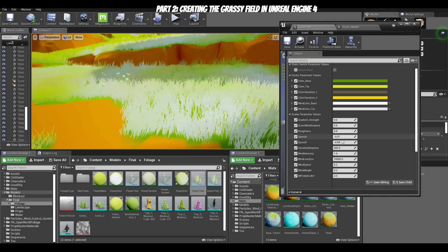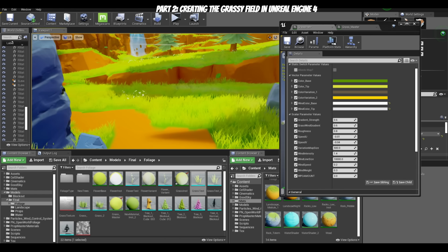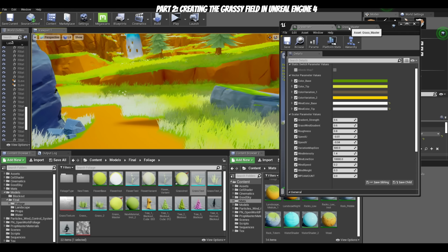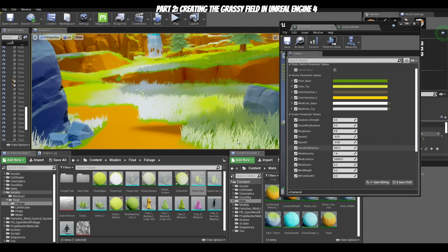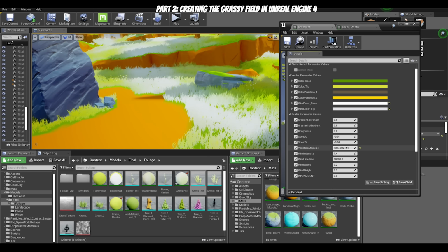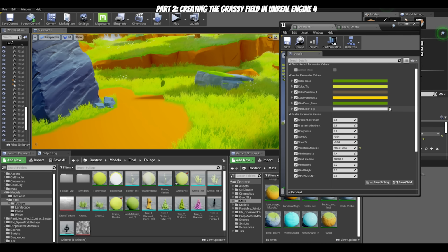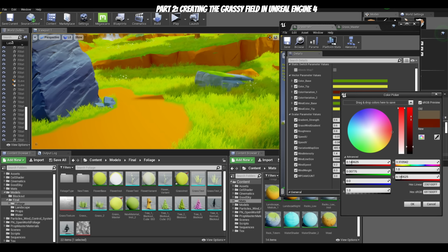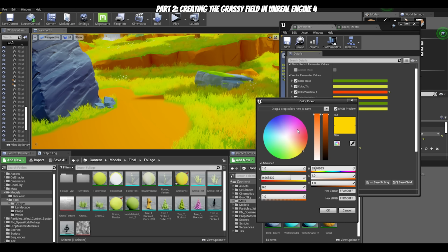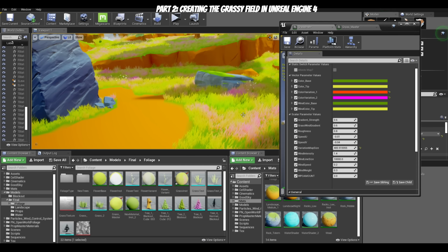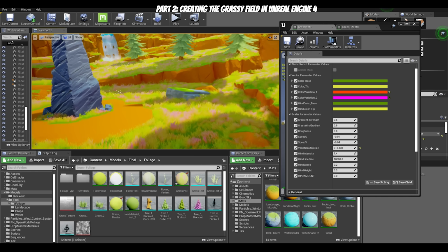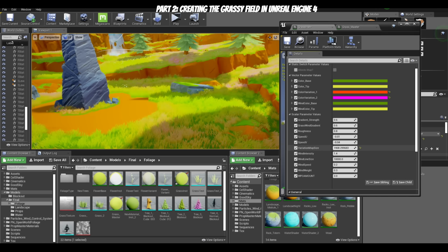Roughness is what you would expect. Speed U and speed V is the wind line speed. Variation map size is the color variation map size. Let me change the color again so you can see how it varies. This is world space, so if I wanted more or less variation, this is larger scale, and this is smaller scale variation, so you can change it like this.